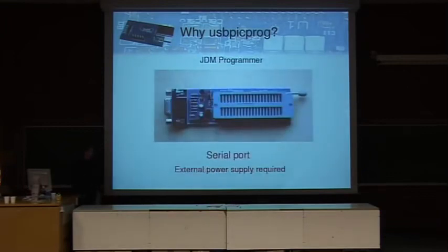There's also another cheap alternative available, which you can also make yourself. It's called the JDM programmer. This one is a serial programmer, and well, does your laptop still have one? Well, mine doesn't. And for most of the serial ports, you will need an external power supply.